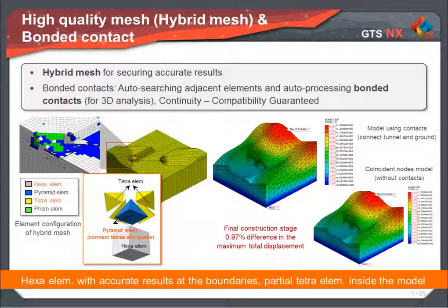Back to some modeling features of the software, a few words about meshing. The new important part in mesh generation is the node connectivity between adjacent elements. If the nodes are not connected, errors can occur during analysis. By applying contact elements, the adjacent elements of non-coincidental nodes can behave as one body. This makes modeling convenient and analysis economic.